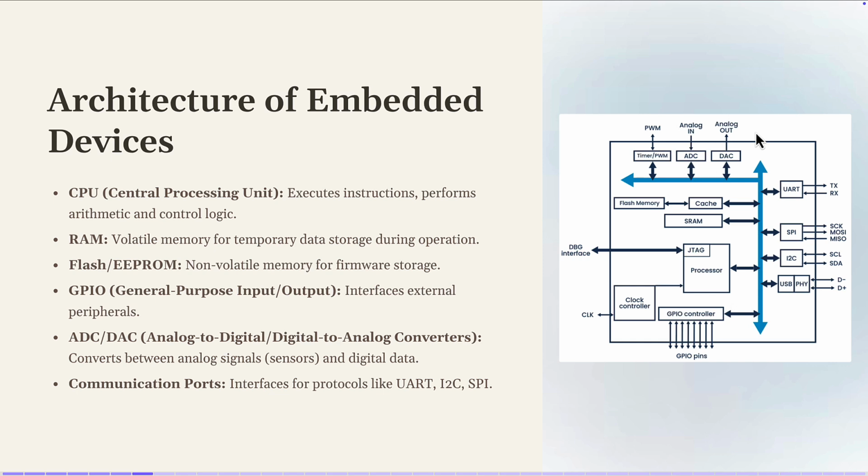Okay, yes, good question. So the GPIO, basically these inputs, are used to connect other devices like sensors. Yes, communication ports like serial, you can connect other devices, but it's more general. It can be Wi-Fi also. They have different characteristics and different shapes to connect other devices. Like if you want to connect a laser with USB, you can use this port, because USB is faster than the GPIO pins. So GPIO is usually for low data rate sensors, like a temperature sensor. Basic things.